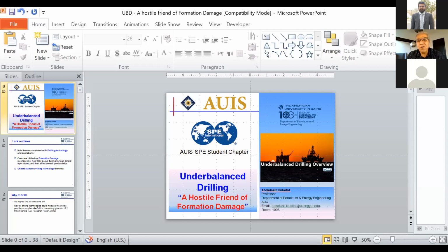Because offshore, we always take care of available space. It's very limited space. Even when it comes to separators, we have no issue, let's say, if we drill inshore, to use a horizontal separator, while if we drill offshore, we have to move to vertical separators instead. So many issues have to be considered when the process is decided, but it can be applied in both offshore and inshore. But the cost definitely will be driven up when you move to offshore.